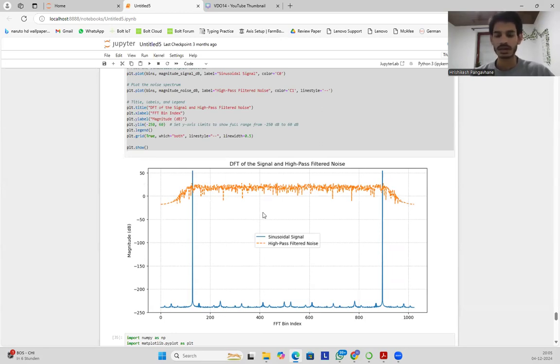Then we said, hey, when we are taking a sequence of n, the ends of that sequence cause the impulse and the phenomenon of FFT leakage. So we are not interested in the end parts of that window. Then we thought of tapering down the end parts of the window and smoothing it down.